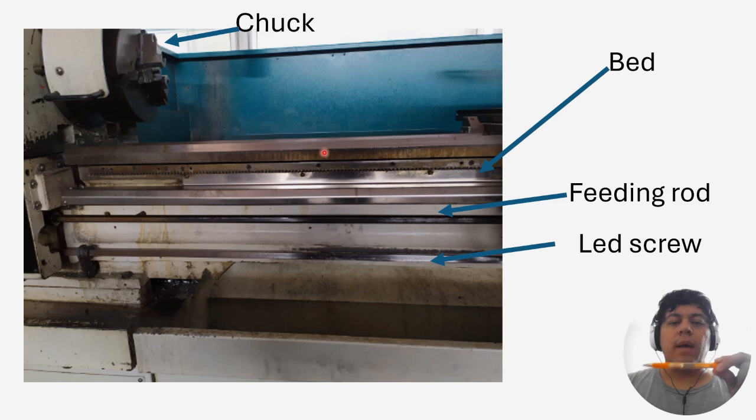However, how am I going to be able to move the whole carriage? Yeah, I know I have the tracks already, but what is going to allow me to move this carriage? Well, we have something called the feed rod. Apologies for this part. I don't know why it's still showing up as feeding, but it's feed rod. All right. The feed rod is going to work for me to start moving the carriage to the specific point where I would like to begin the manufacturing process.